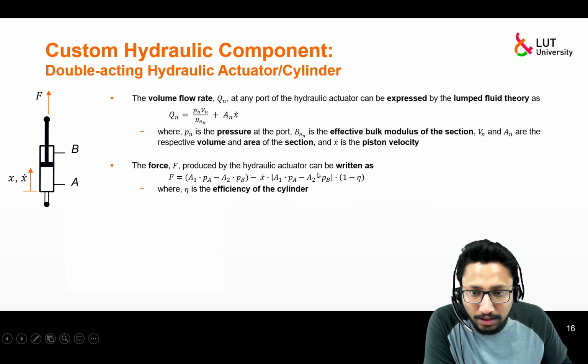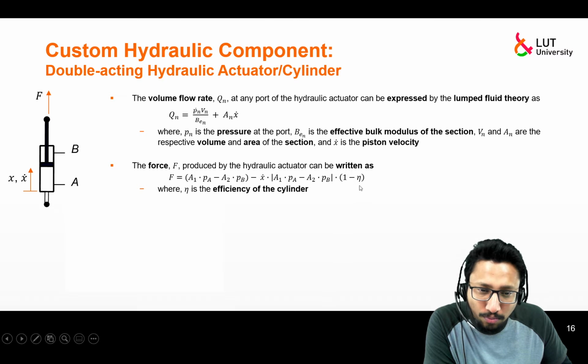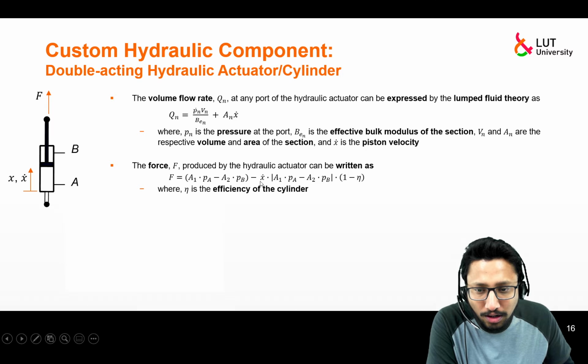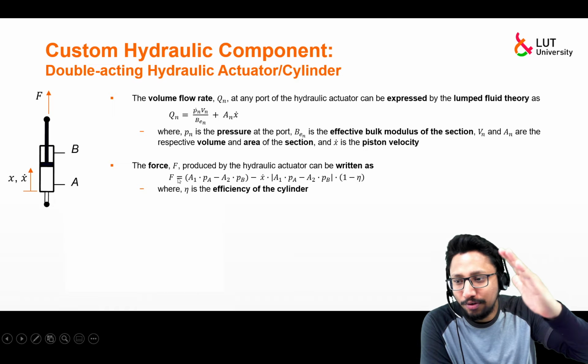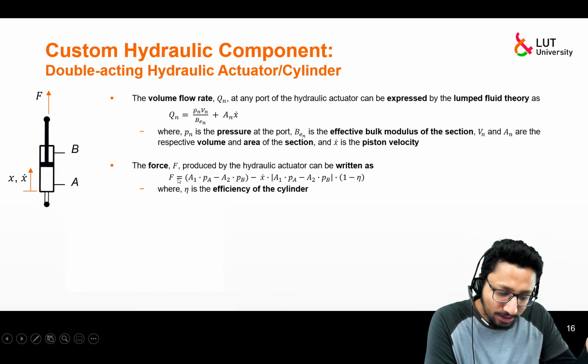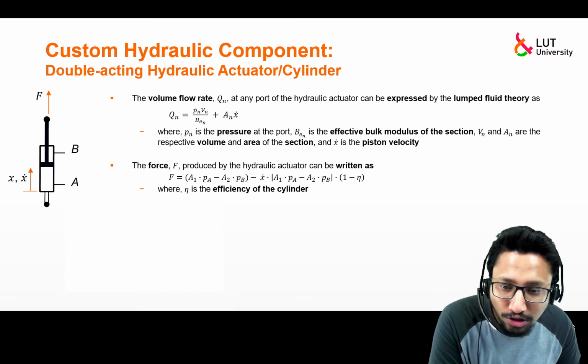So normally friction models can be improved versions as well, but here we have a pressure and velocity dependent friction model. Since it's pressure dependent and pressure fluctuates, the friction model fluctuates, so the force fluctuates and your entire system will fluctuate, as it was happening even in your last simulation work.